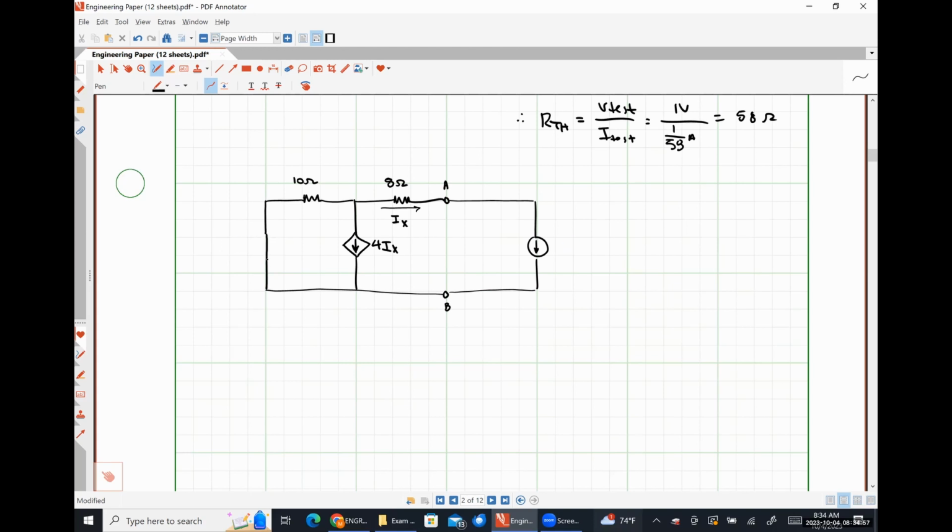Sorry about that. What value do we want to choose for our test current? 1 amp, sure. Seems reasonable. So 0 would be an open circuit, which means we're not applying some sort of test signal to use. So it can be literally any value but 0, because if we choose 0, we're not exciting the circuit and seeing the response we have.